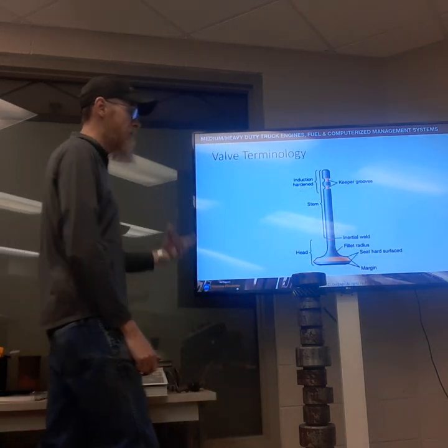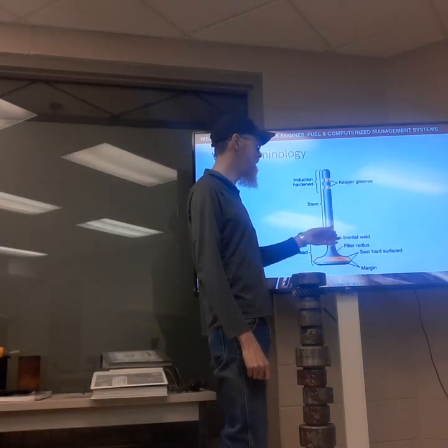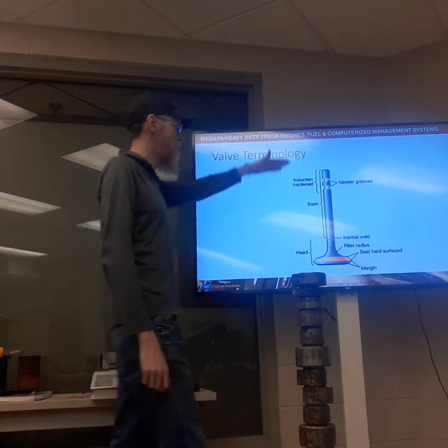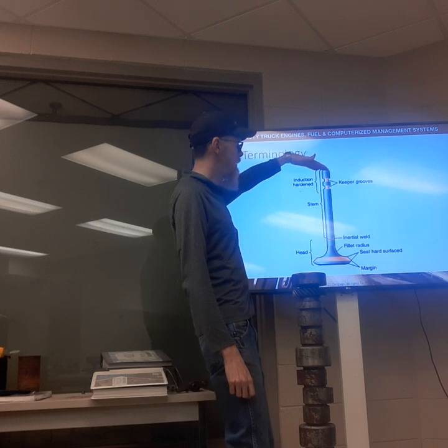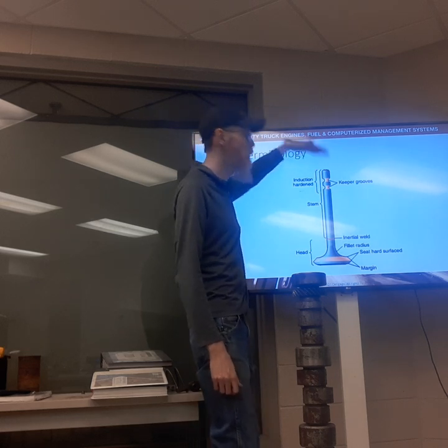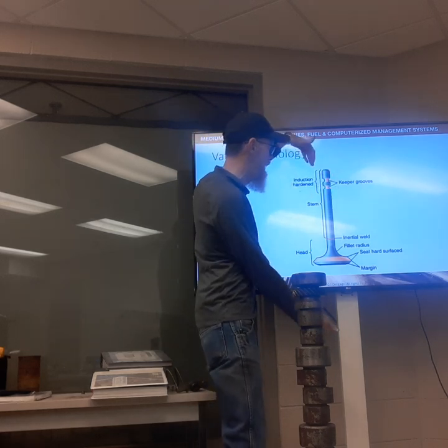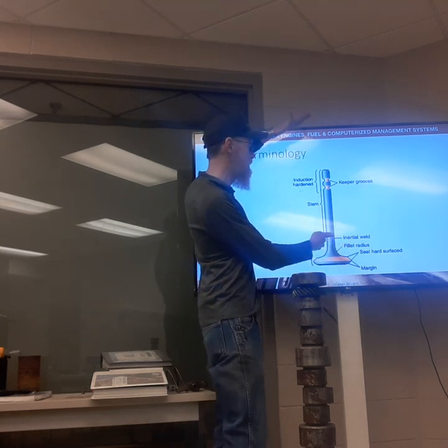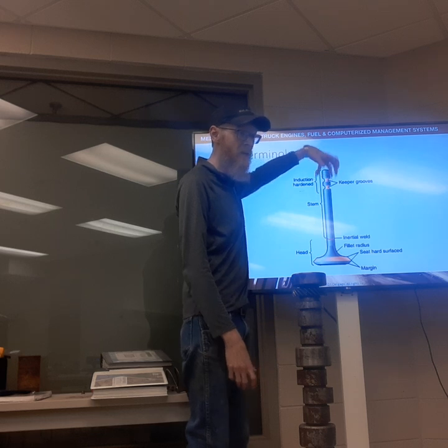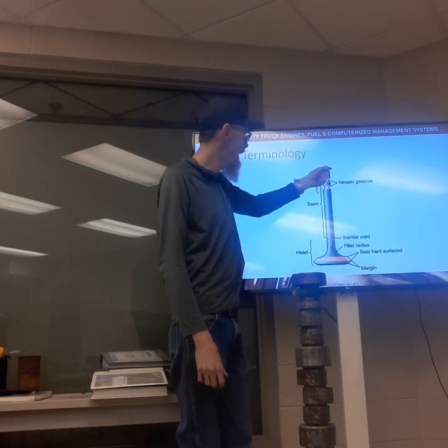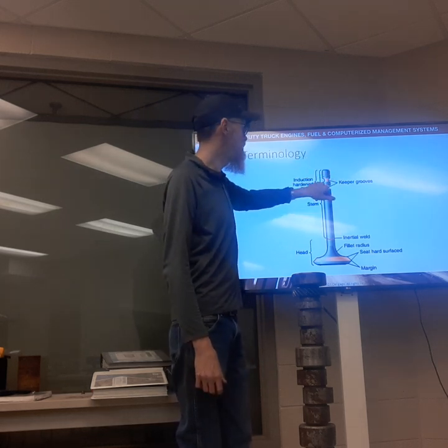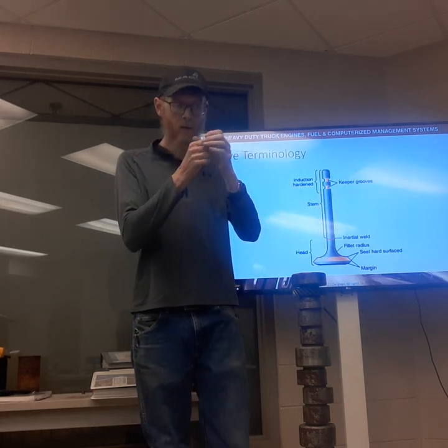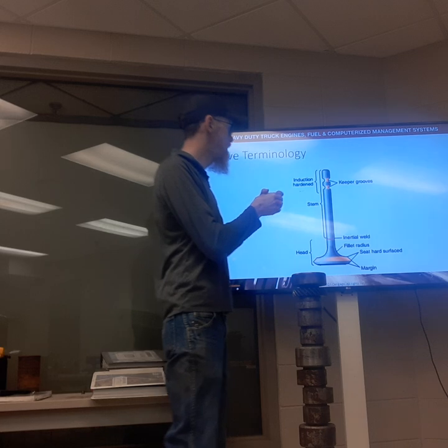That's ultimately how we retain the valve to the valve spring on the top side, so that when the rocker arm is done pushing down on the valve and opening the valve, when that valve needs to close, that spring needs to have a grip on that valve. Those keeper grooves are where that spring is gripping onto that valve.